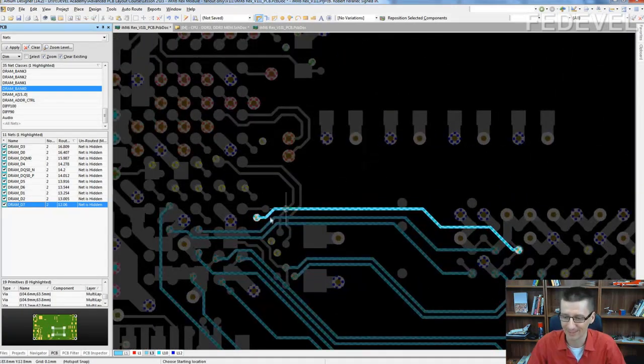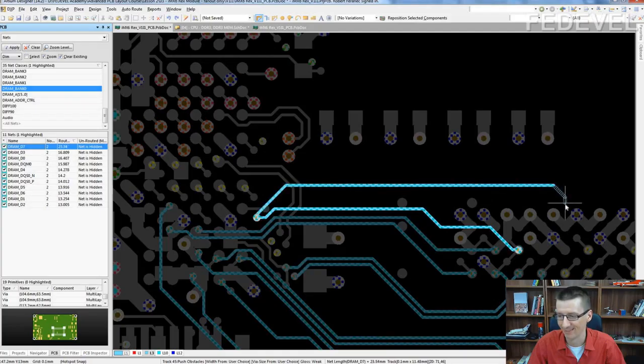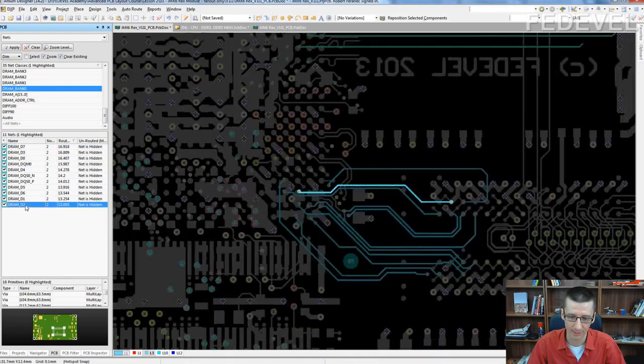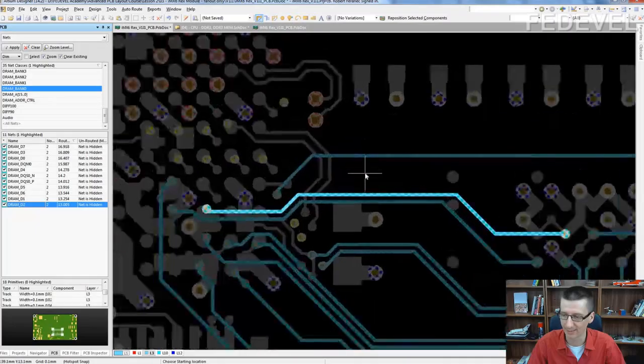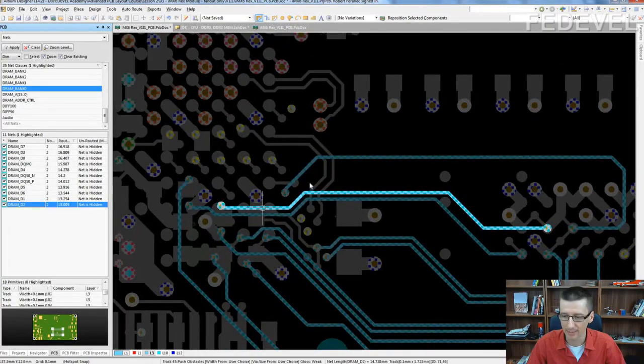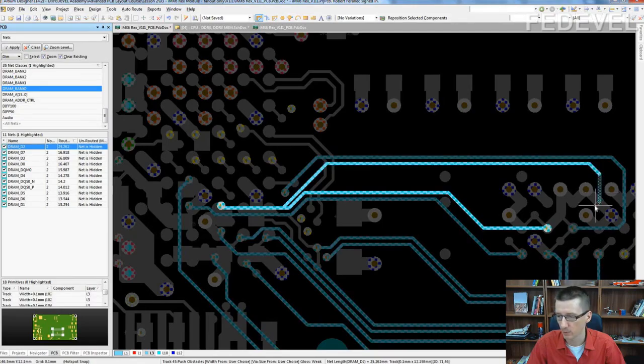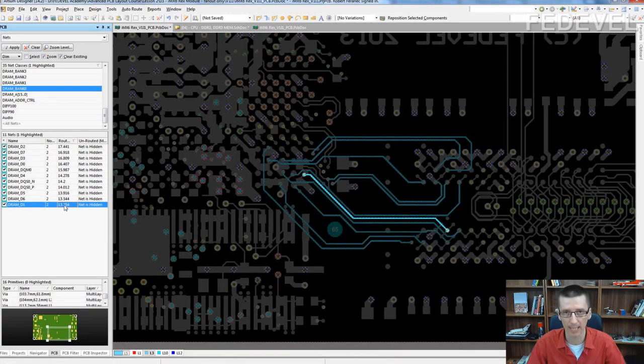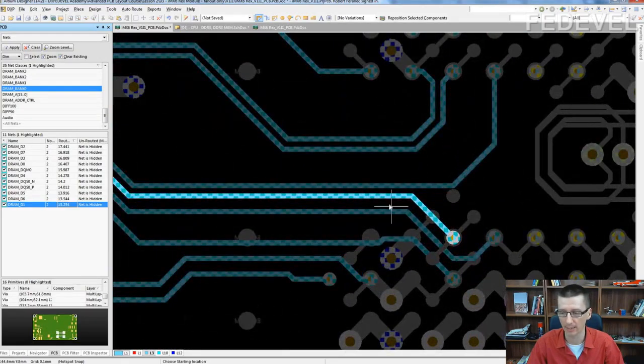I can do it longer because I don't have the yellow group routed. For you it will be more difficult. Then click on the shortest one again and make it longer again. I call this preliminary length matching. At this stage we only would like to occupy space. We would like to see that we will be able to achieve the target length.